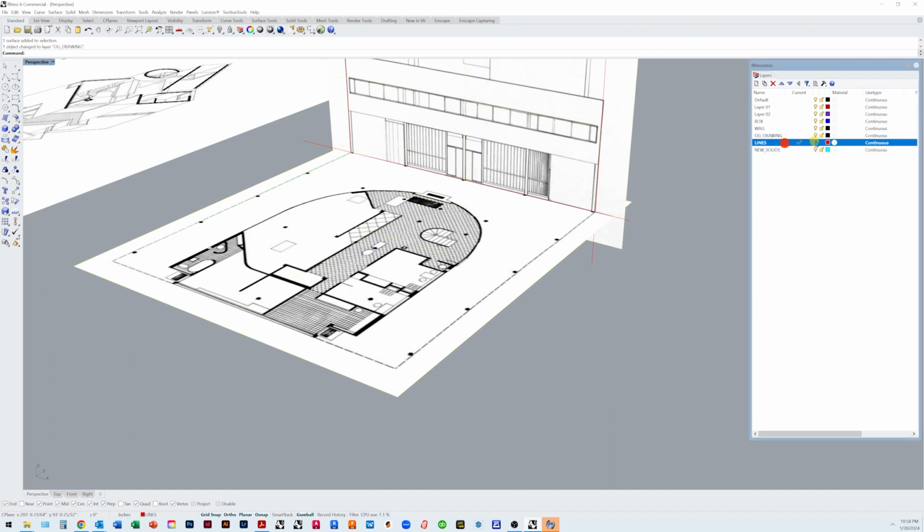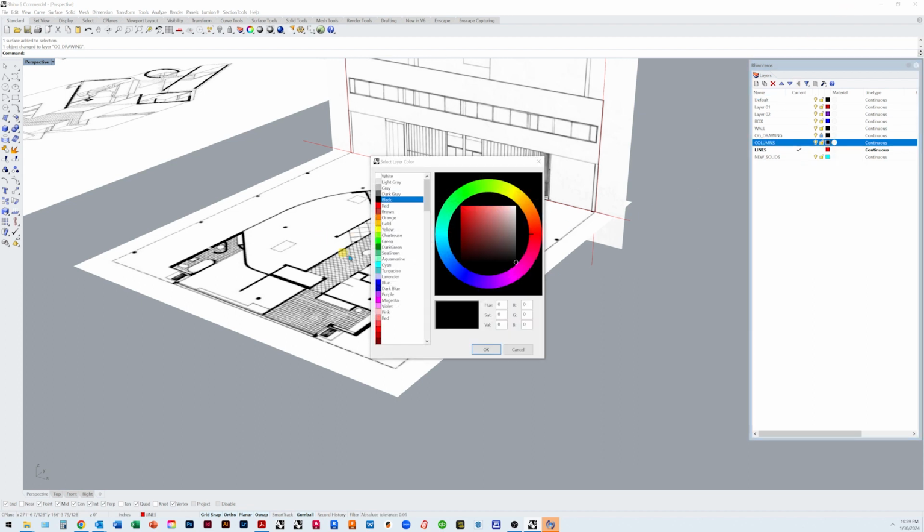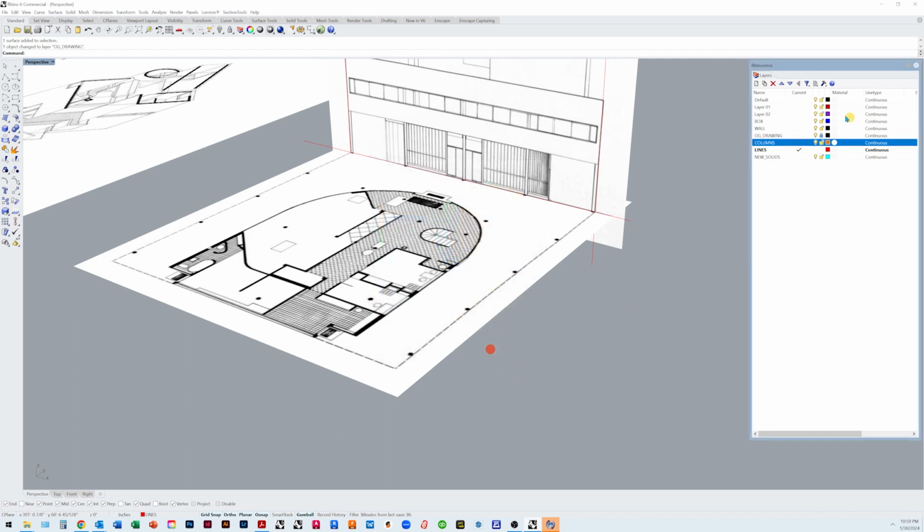And maybe let's go in and lock that layer so that we don't move them around and mess up the scale. And then let's start drawing parts of our building. So I'm going to start with these columns. Draw a column. I'm going to make it orange. Double click that layer so I'm on it, and then I can go here to my solids.